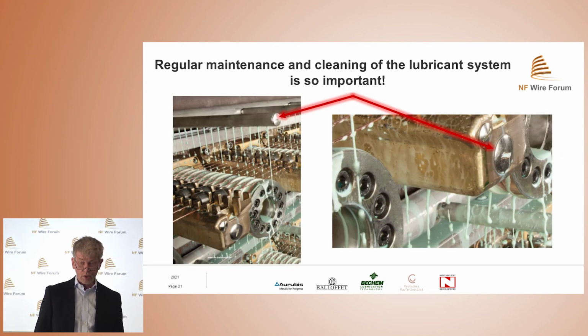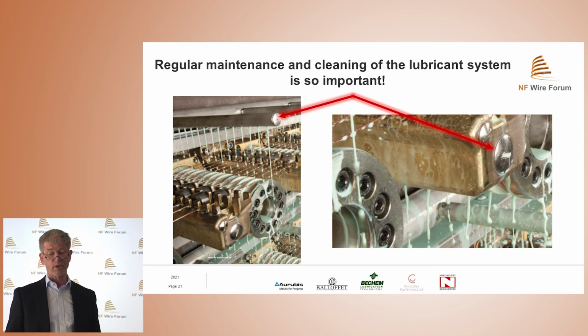Very important also is the lubricant system. A regular maintenance and a regular cleaning of the system, so that there is always enough lubricant on the wire and on the capstan.